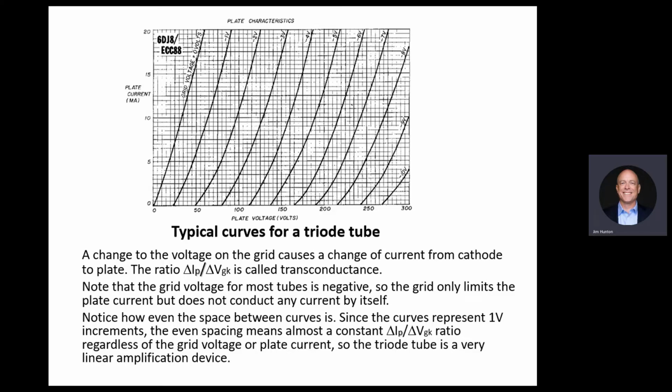We can measure that. And in the lab, John Crow will tell you, he'll put a device on it and see, okay, this is how much distortion. Change the conditions, say, okay, I don't want it here, I want it there, and see, well, is this a better point? And you find basically where it's ideal for your circuit. So this is the biasing concept. When you talk about biasing a circuit, this is what you do. You determine, you fix the operating point.